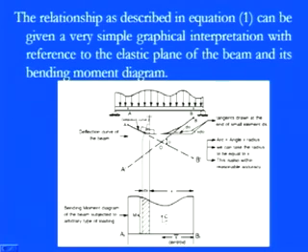So we have the centroid, and with the kind of variation you see here, we have the bending moment diagram in this way. So this is the kind of deflection in this particular beam. As you can see here, this is the deflection curve. It has a maximum value at the center position, and starting from zero deflection at these two supports, it comes in this way, and if you put the tangent, then you can simply locate the origin of those things. And these always go for the arc, that is, what the arc length is in this particular deflection curve.